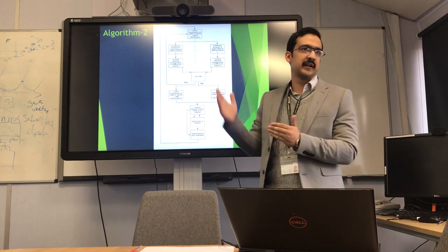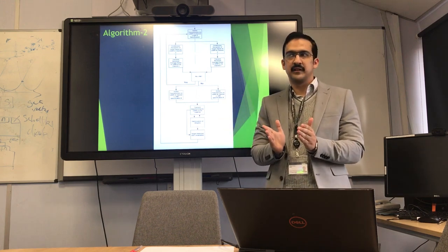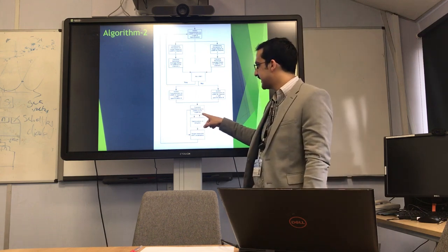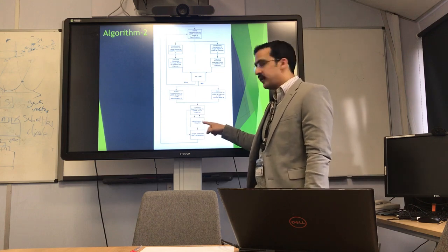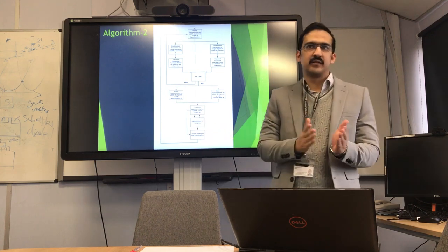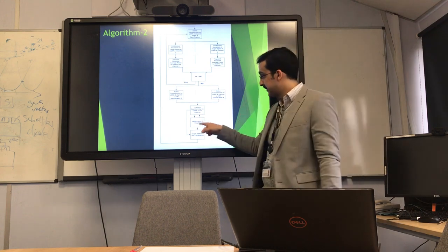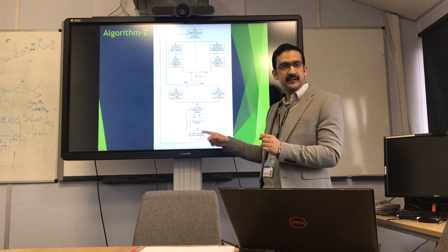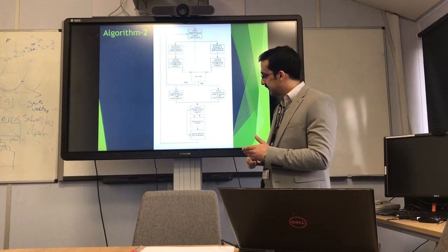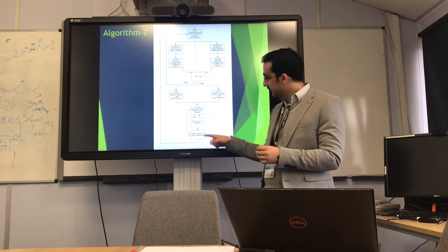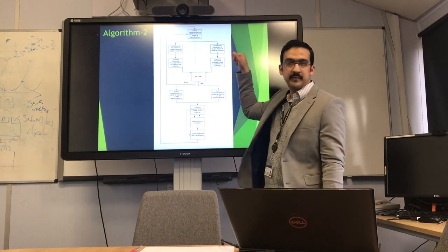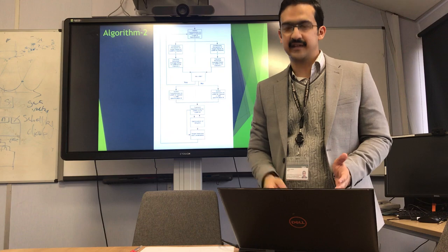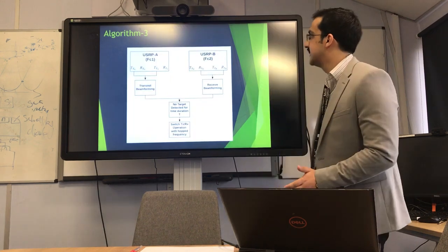So it's kind of a beamforming that can take place, and no device would remain idle at any time. So there is transmit beamforming by USRP-A and USRP-B, and the optimization of weights. As you know, in order to steer the beam, you have the corresponding weights, and you optimize those weights. I'm in the process of formulating the weights for the transmit beamforming purposes, and then the targeted localization, and the same process follows. So it's a very easy solution, but again thanks to the flexible nature of the SDRs.